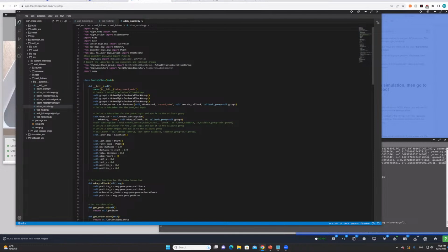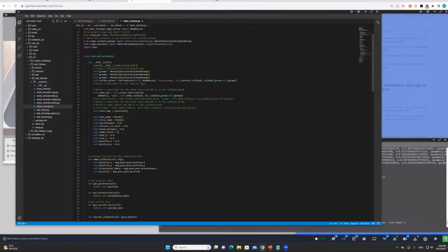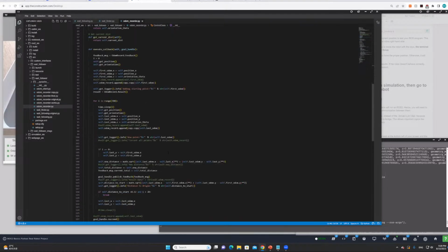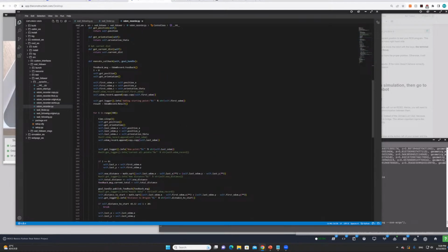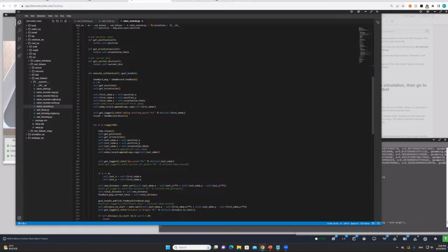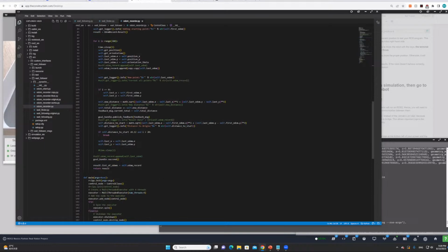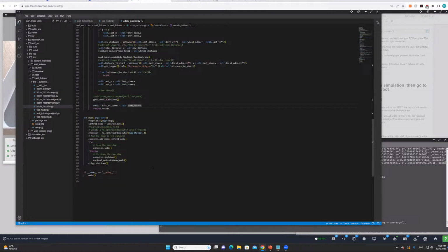Then we start the action server, and then this is subscribing to the odom data. Then I define all those variables here. When the execute started, they follow this routine so that they're recording the first point, and then after that they keep recording the next data point, and then after that they're sending the succeed result, and then they are sending out the list array data, right?